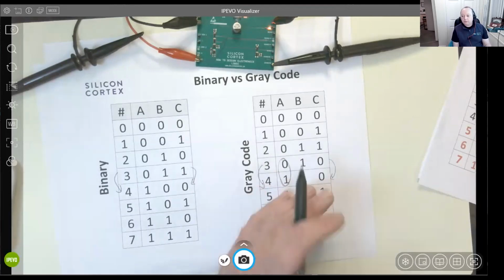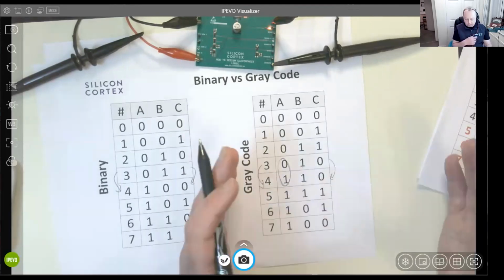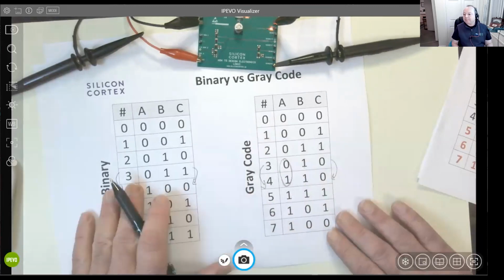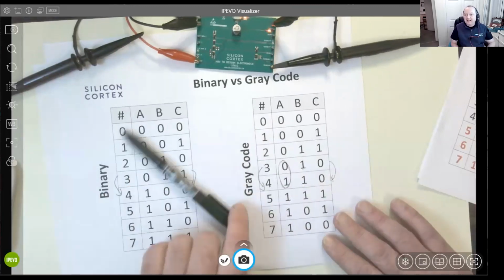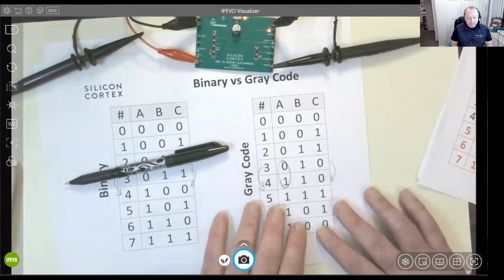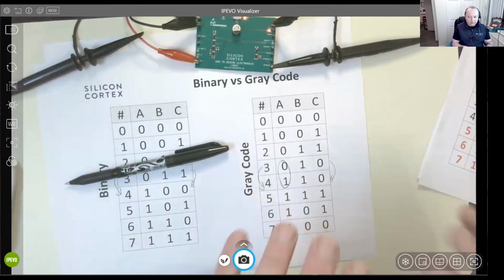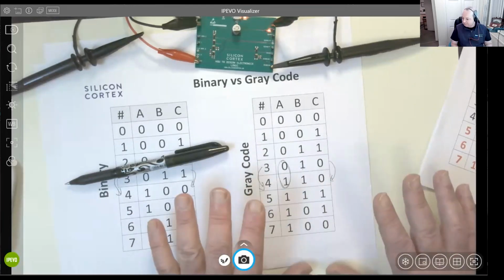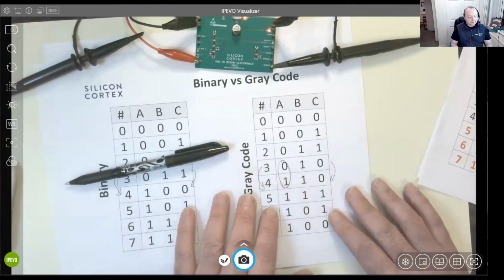But it was on an I2C port, which is a communication bus we'll probably get to talk about in Series 2, when we talk about I2C and SPI. The capacitive loading they put on their I2C line meant that when we started adding other I2C devices, it completely destroyed the integrity of the I2C signal. That had us going in a merry circle for quite a while, trying to work out what it was.